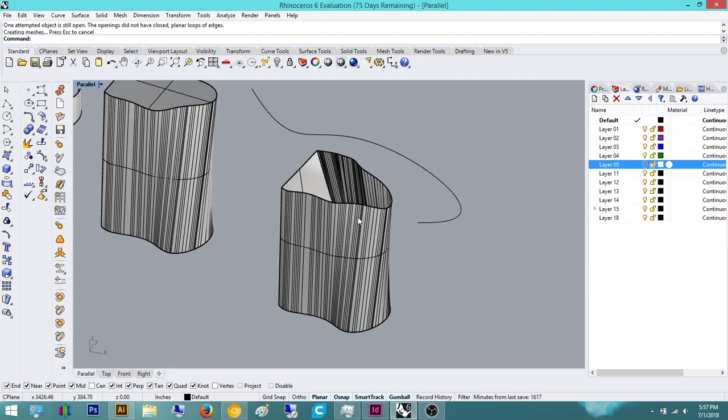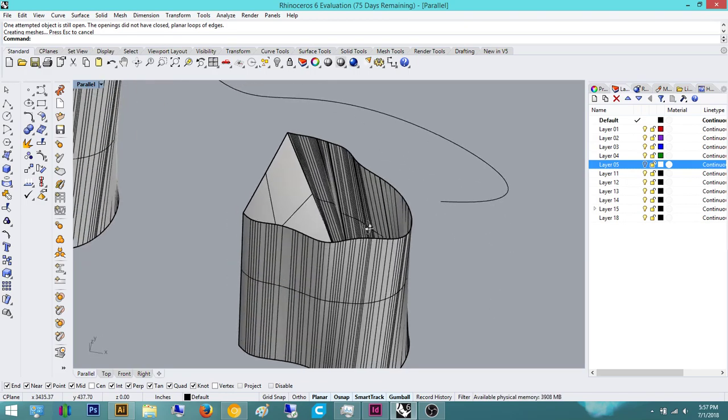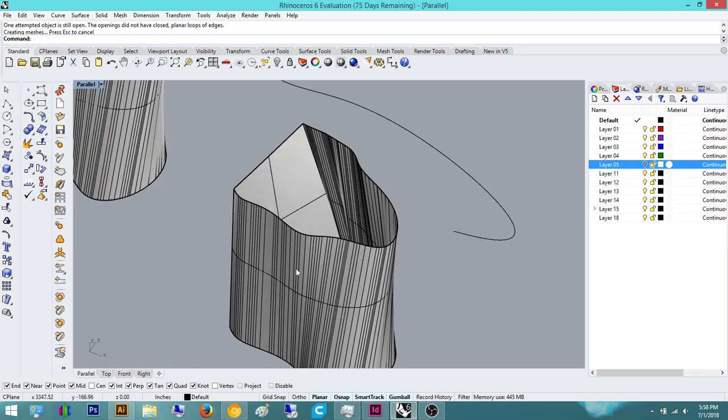Anyways, so you're wondering, all right, well, this object's solid. How do I cap it now, or how do I make it solid now? It doesn't really make sense. How do I do that? And the answer is, there are multiple ways to do this. The way I found the easiest is through edge surface. We talked briefly about edge surface in surfaces, but I think I can go over it in depth in here. We can use edge surface also to create the quote-unquote cap of it.